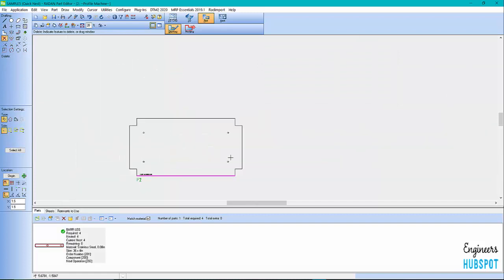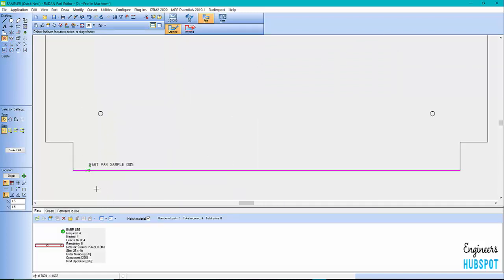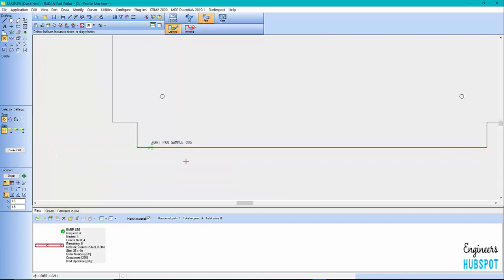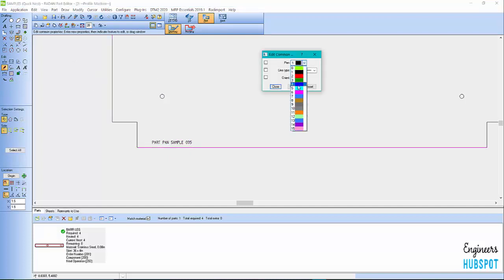Right, so from here, because that's just a regular text, I'd need to realize that in situ. In AutoCAD you may call it something like explode, right? So I come in here and I go realize in situ, and I say letters, give it a tolerance, do that, and then I'll just come and change my pen properties so it's a different color.